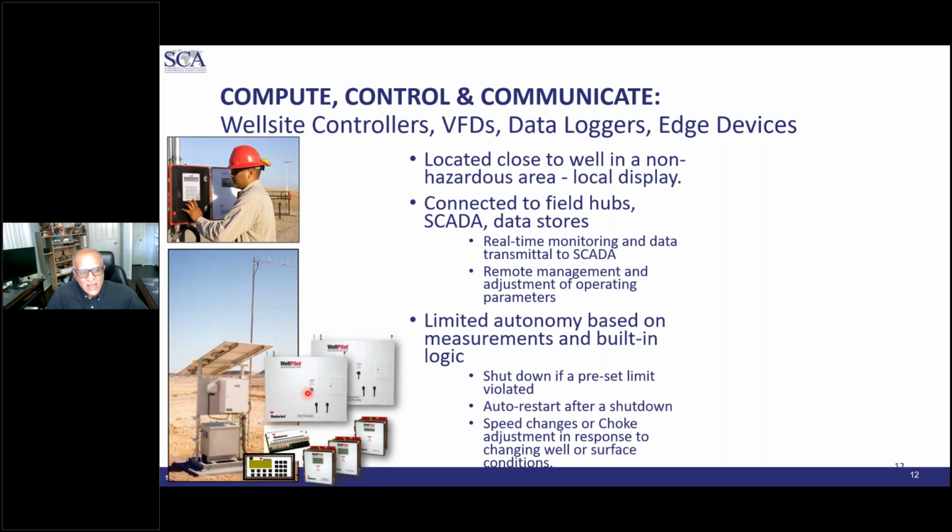For example, if it's a tank level measurement connected to this controller, and it senses that tanks are reaching the critical level, then it can stop the pump. Or if the liquid level is below a certain level, then it can start the pump. So there is quite a variety of actions that can be performed by these controllers, and they are becoming very, very sophisticated. For example, variable frequency drives can vary the speed of a rod pump throughout a stroke.